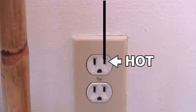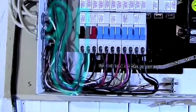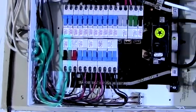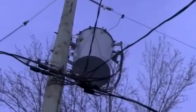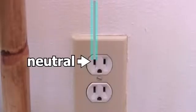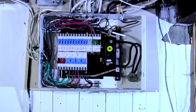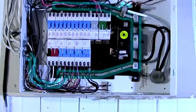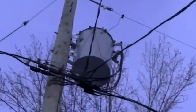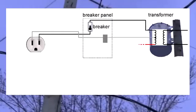Behind the hole called hot, you'll find a wire that runs behind the walls, and eventually goes to a breaker in your breaker panel. From there, the electricity goes behind the breakers to one of these thick black wires, and then outside your house to a transmission pole and transformer somewhere. The other hole, again called neutral here in North America, also goes to that breaker panel, but not to any breaker. Instead, it goes to this metal bar. From there, the electricity goes along this thick white wire, and then outside your house to the same transmission pole and the same transformer. Here that all is in a diagram.